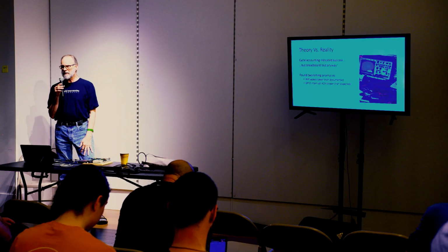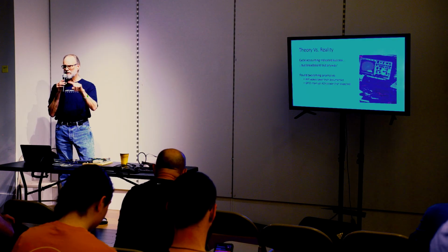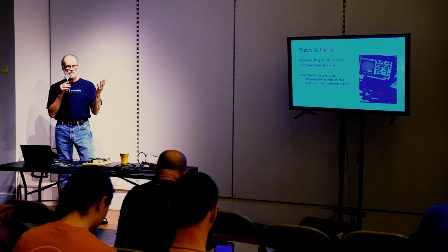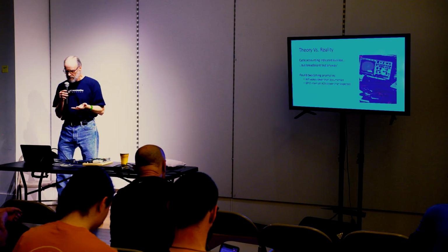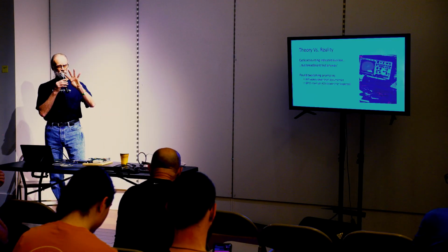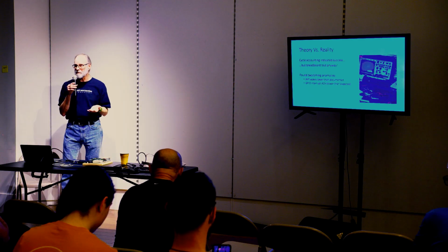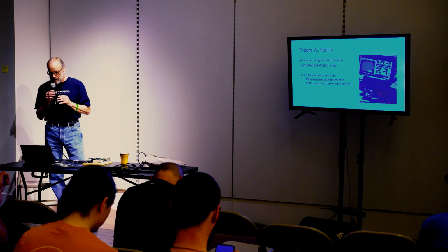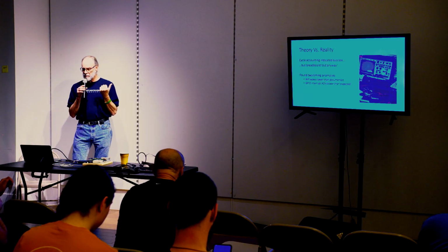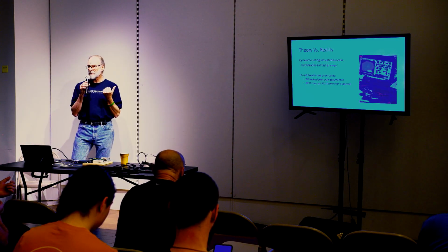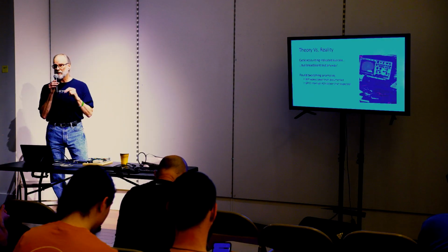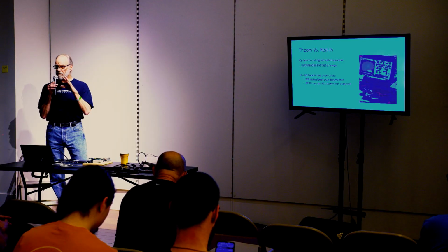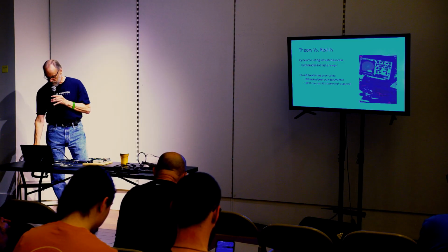And it's like, okay, what does that mean? Like 1 to go to sleep and 1 to wake up? Or 2 to wake up? It wasn't clear. And in fact, the answer is it takes 4 to wake up. And that's not documented anywhere, but that is reality. And also acknowledging the GPIO interrupt was slower than I thought. That took 5 cycles, and I was expecting 2. It didn't matter. All you do is update the accounting, and everything still looked right, so off I went.